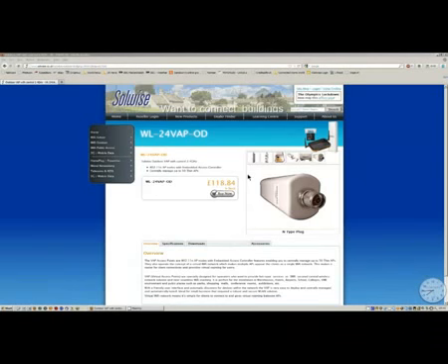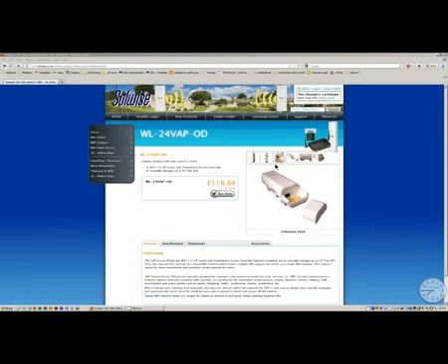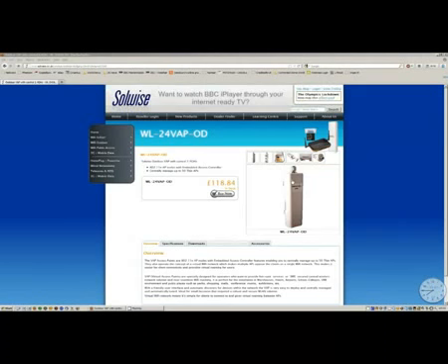The VAP outdoor unit, the one we're looking at here, is a standard outdoor CPE type plastic housing. We've got an end plug on the top, which is good, so we can directly connect antennas to the top of the device. In addition, it also has a small low gain directional panel built into the front of it. It's not a high gain directional panel, so the advantage is it gives a nice wide beam of signal. I believe it's only about 10 dB, but not huge. And through the software of the device, you tell it whether you want to use the indoor or the outdoor antenna.